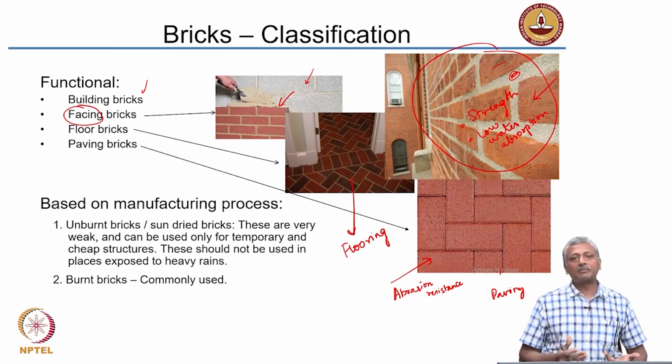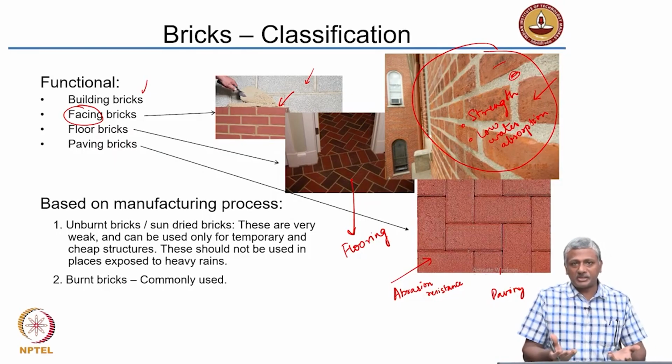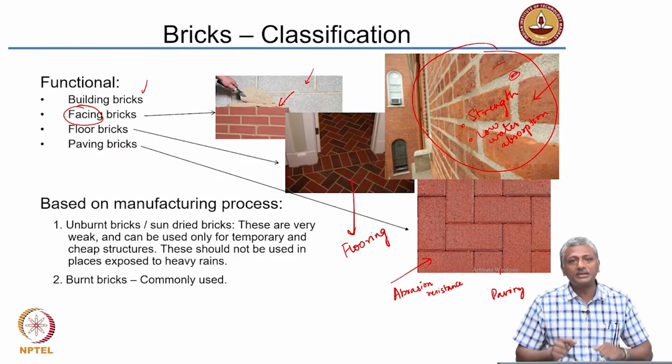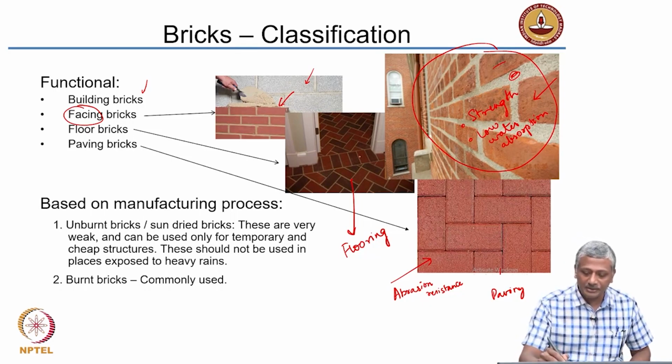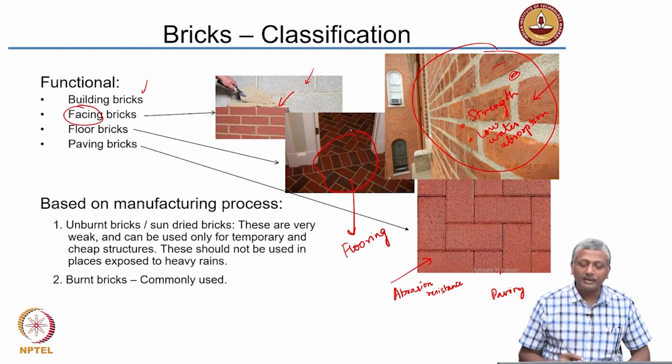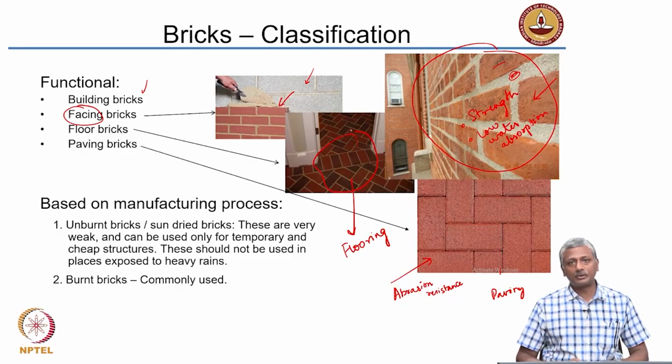So, these are designed primarily for abrasion resistance, and they should be strong enough to be scratch proof, especially in the house, right. When we start moving furniture, you do not want the floor to be scratched by it. So, again the bricks should be designed adequately enough so that they are scratch proof. And you can see that with the use of different colors in the flooring brick, a very nice pattern has emerged, right. It is still looking quite beautiful. You do not really need to have good looking tiles to make a very good looking floor. You can actually have bricks also, okay.